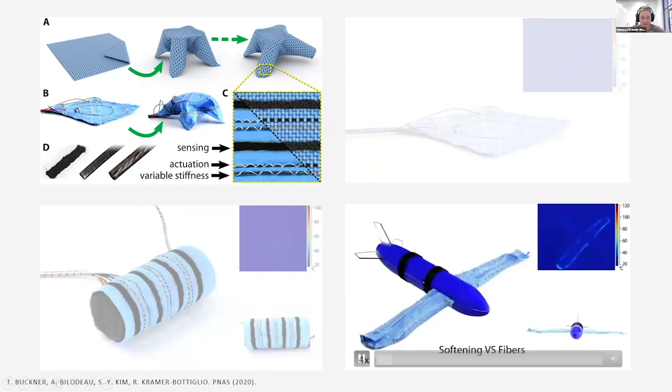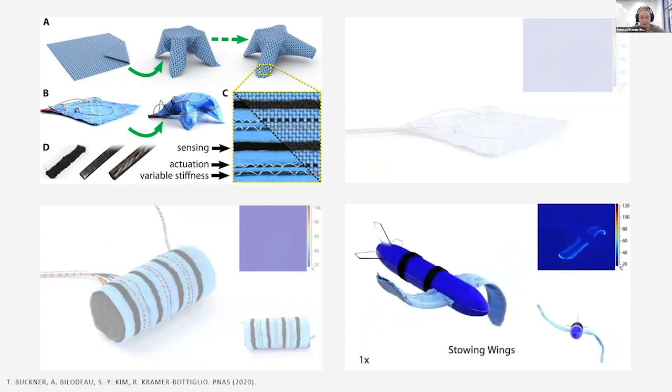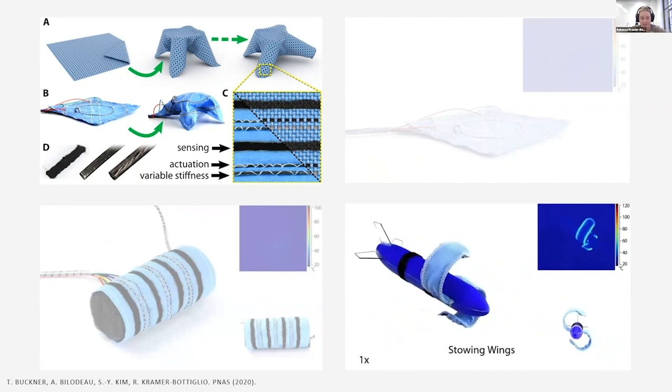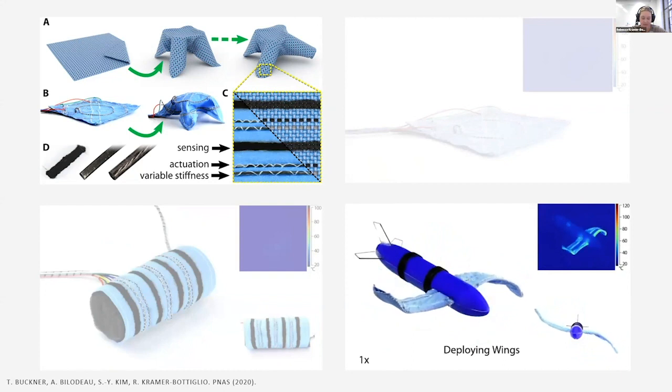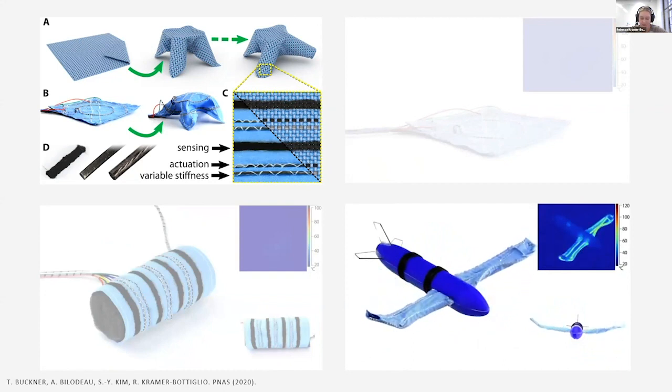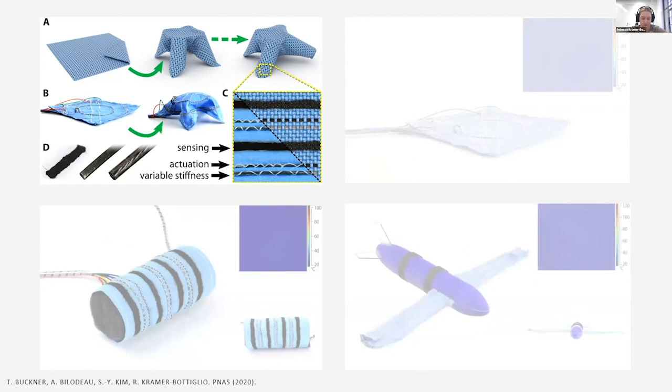And finally, in this last demonstration, we have self-deploying airplane wings in a fully untethered system. So this demonstration was inspired by the 1903 Wright Flyer, which also had fabric wings. The wings in our demonstration are seated into small slits on the side of the fuselage, where we put all the additional circuitry, microcontrollers, and batteries. The fabric wings curl to wrap around the fuselage for compact storage and uncurl into the deployed rigid state with the wings extended. This demonstration shows how a robotic fabric can self-stow when not in use and might be useful when low storage volume is required.